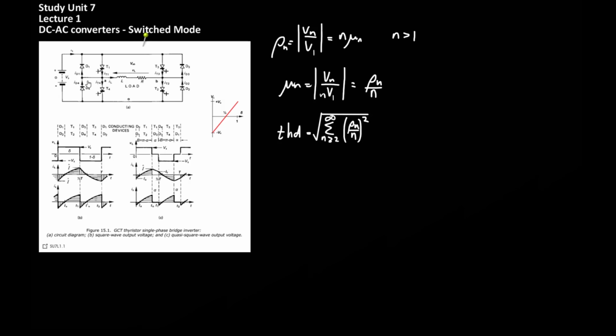The diodes which are present in each leg of the bridge are not necessarily needed, but if there is some inductive property in the load, then these diodes act as freewheeling diodes, so any energy that remains in the load is allowed to pass through the diode during a switching transition. So this bridge circuit can operate in 2 modes. There is a mode where it produces square wave output, and there is a mode where it produces a stepped square wave output.